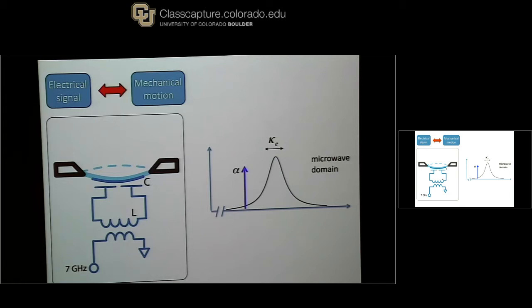So this electromechanical system, I guess this is the first time I've talked about it separately. It also has a coupling that turns out to be about 10 megahertz per nanometer for, say, one of our typical devices. And so that is on order of what we get in the optical device, and so we have an interesting parallelism. And here, let's see, I think I'm going to start using A for the microwave mode, because ultimately the microwave mode is the one that we'll be starting with. B will stay the mechanics, and then I think I'll use C for the optical eventually.